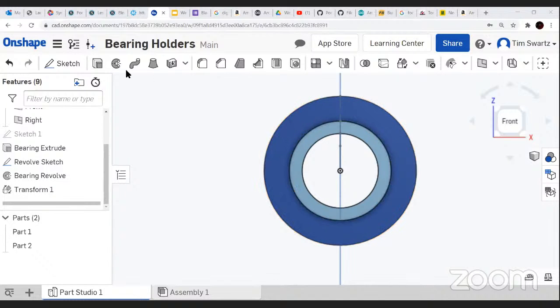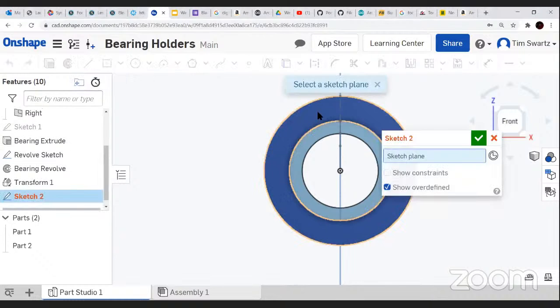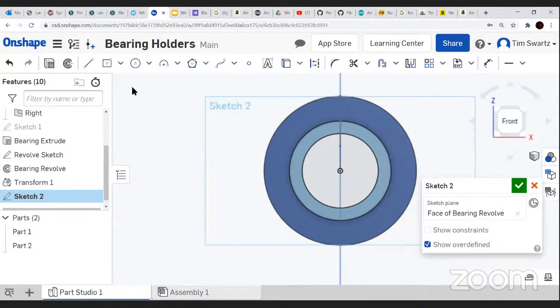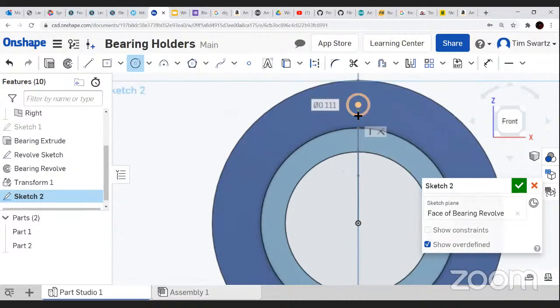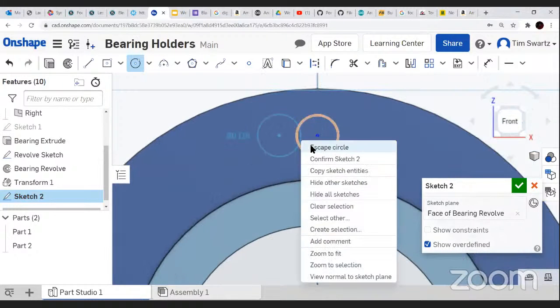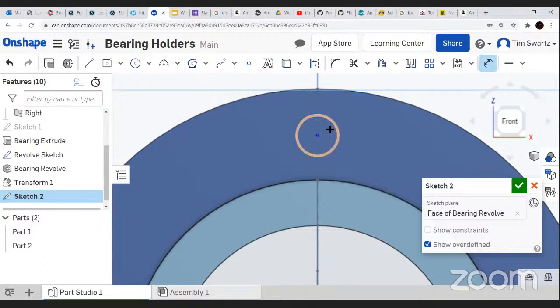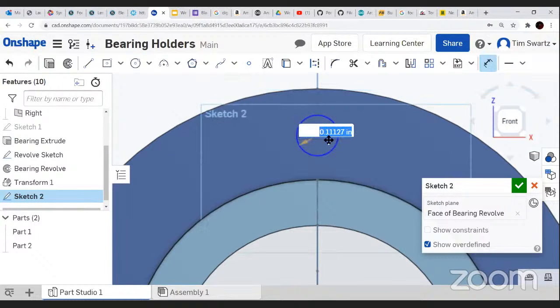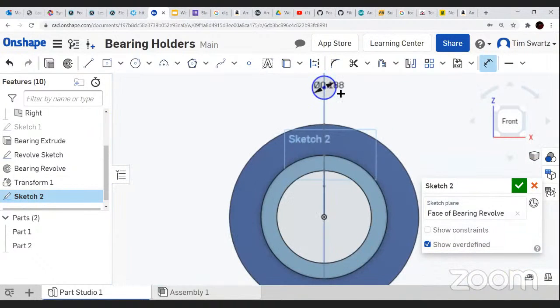So what we're going to do is sketch on the back side of our part. We're going to put a hole. We're going to go on center for the first one. And that hole diameter, we'll probably use an 8-32 screw. So these are going to be 0.1875, 3/16 of an inch. And I'm going to drag that back down.